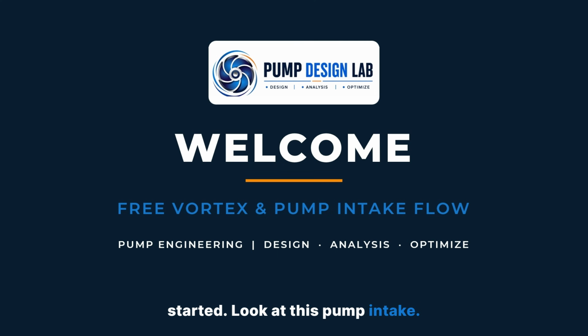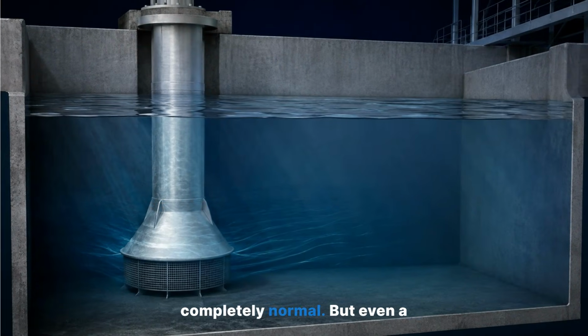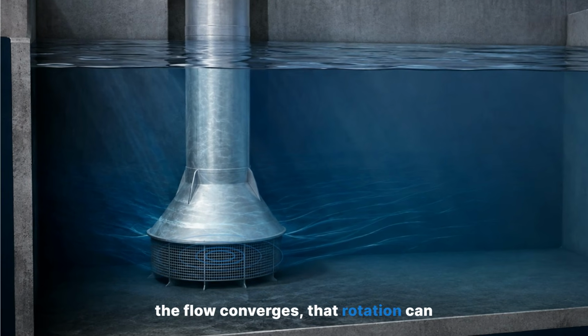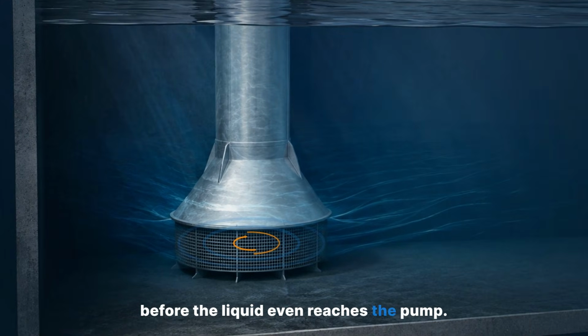Look at this pump intake. At first, the water around it may appear completely normal. But even a small amount of rotation in the approaching flow can become important as the liquid moves toward the intake. As the flow converges, that rotation can become stronger. And under the wrong conditions, what begins as a simple swirl can develop into a strong vortex near the pump intake. This can disturb the flow before the liquid even reaches the pump.